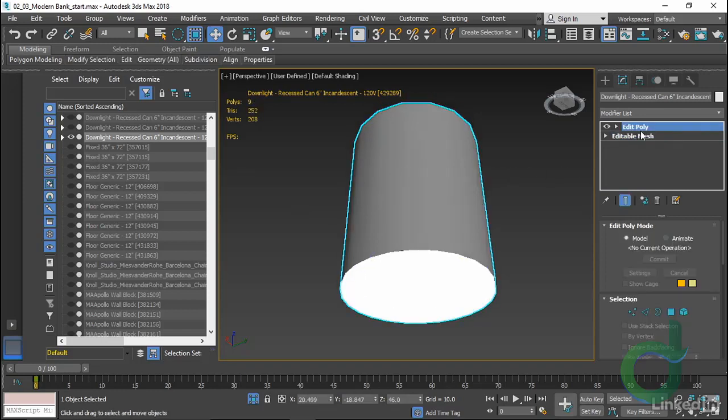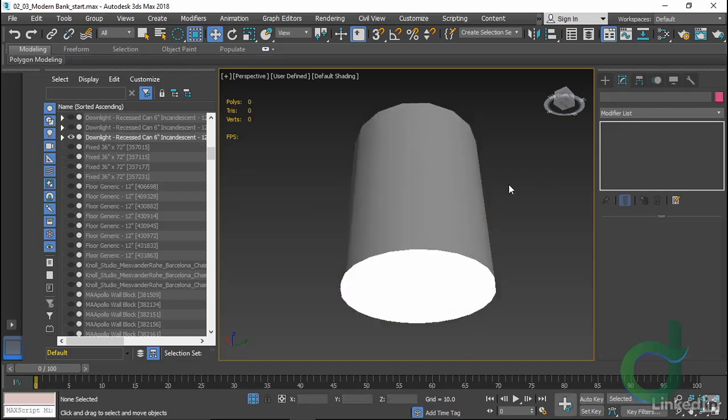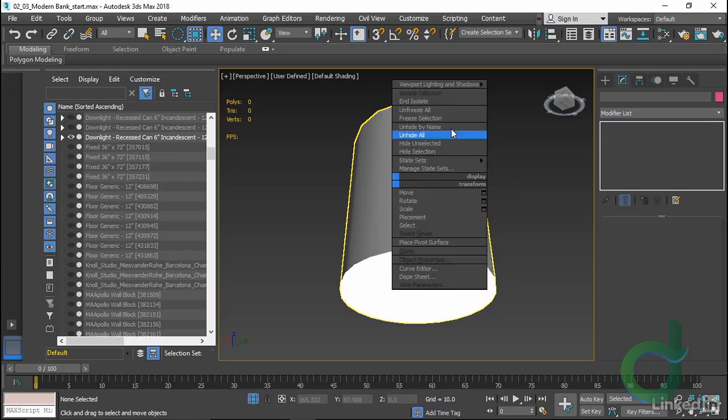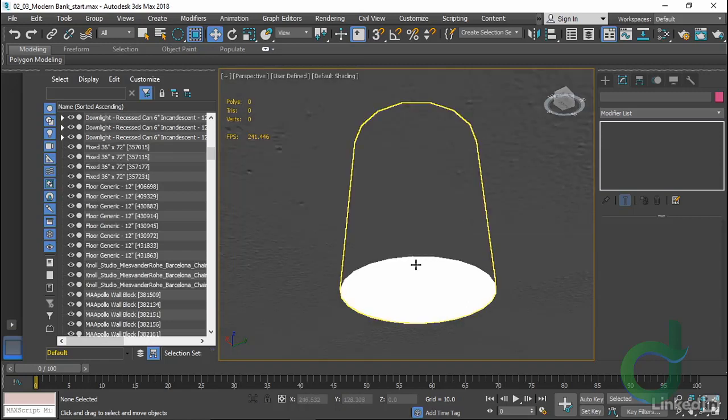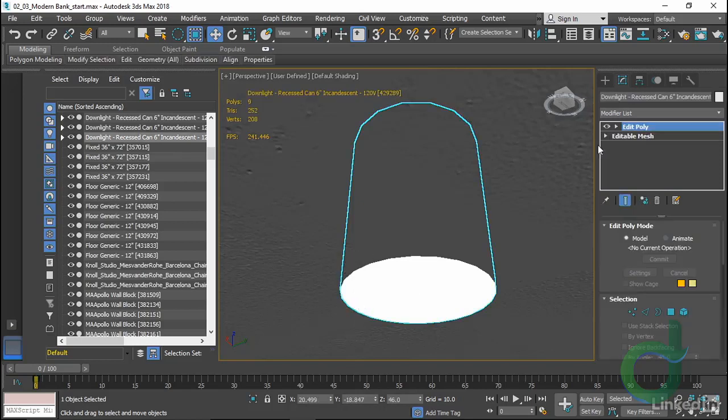Now, if you're asking why go through this, remember that this is one of 5 in this rendering, and conceivably in a scene you may have dozens, and so taking off, let's say, 20 times 120 polys is a significant savings. I'll right-click and exit the isolation, and now I'm back here looking at my ceiling. And again, there's that diffuser we can take off if we need.